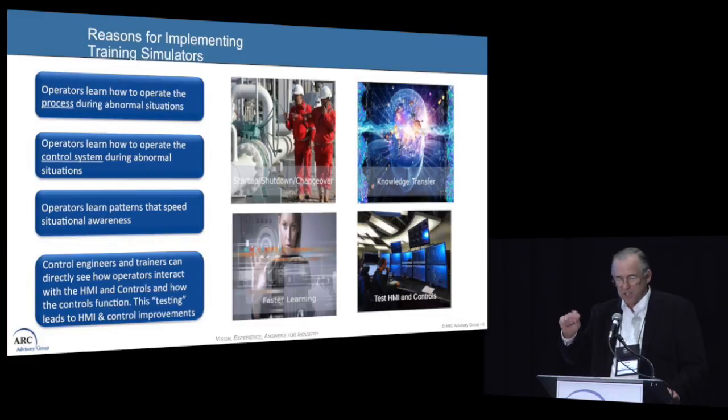And you go through some checklist and everything is passing and you say, all right, it's ready to install, and we start up the plant. But when you test with a control system in simulation mode, and you walk through every normal operation, a startup sequence, a grade change, a shutdown, all abnormal situations, also failure modes, you find a lot of mistakes in the control system.